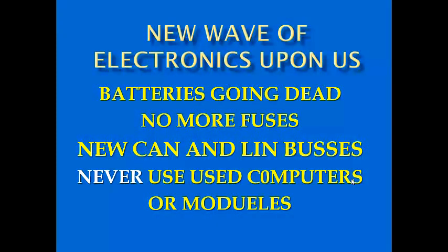I strongly suggest you don't use used computers or modules on the newer vehicles. And of course, I'm just making the suggestion. You do what you want in your own shop. But a lot of these vehicles now have security codes as we're sharing data by CAN bus. These security codes are vehicle and computer specific. Put a used computer on, and it will be corrupted as it recognizes it's not a legitimate computer for that vehicle. At the same time, it could take out other modules or computers on the car and end up costing thousands of dollars in repairs. Again, that's totally up to you.